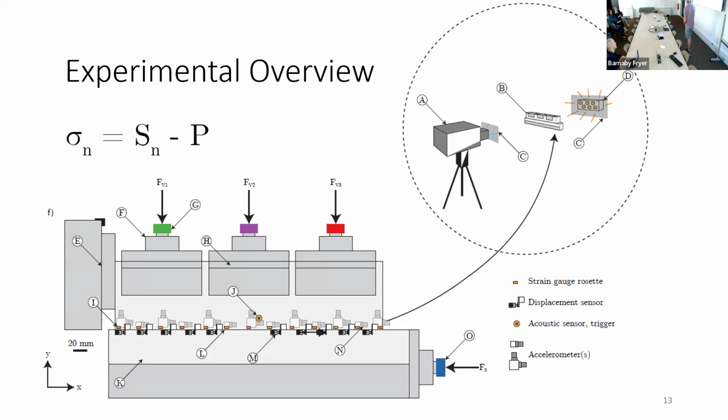And basically these pistons are independent. We can control each one of them individually, and they're also not connected as their sample holder, such that we can really put a high stress here and a low stress there, for example. That would be something we could do. We have then a fourth piston, which is applying a shear force here and a shear stress eventually along the fault. And basically by charging up these three and then this one, we can then create a seismic event along the fault.